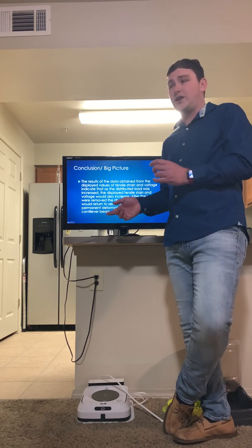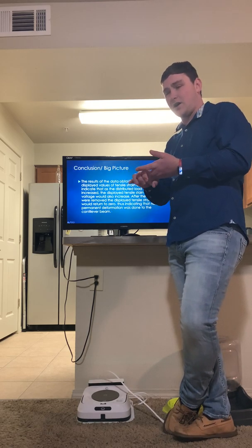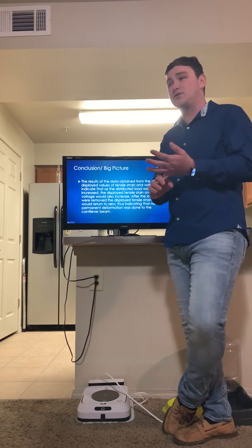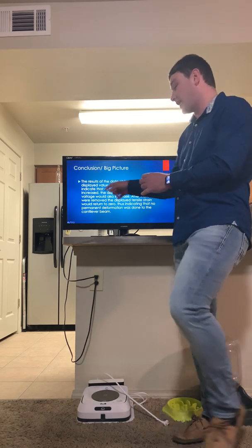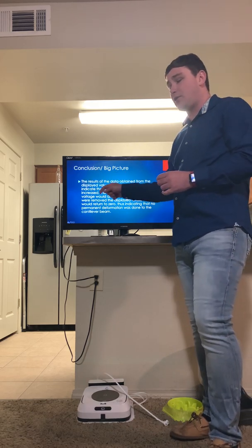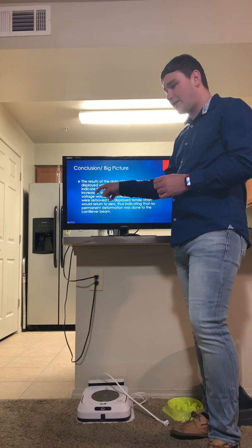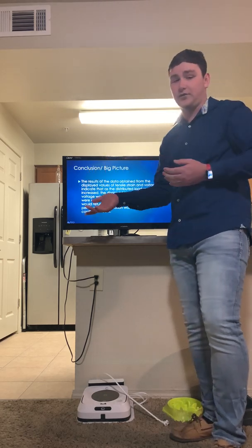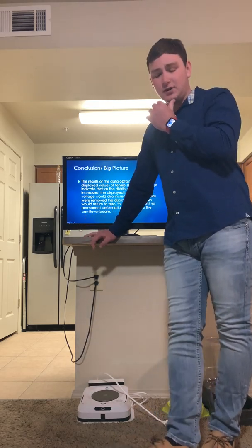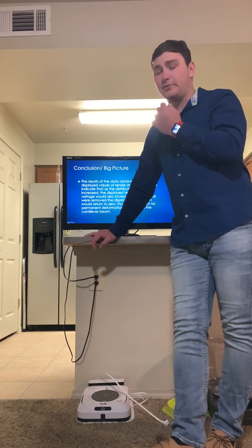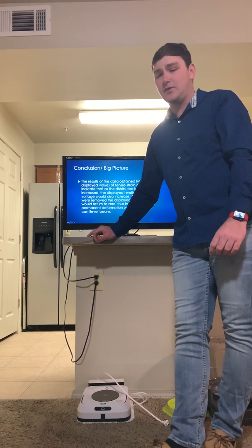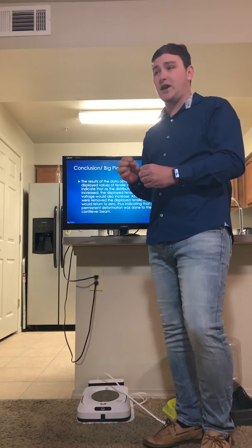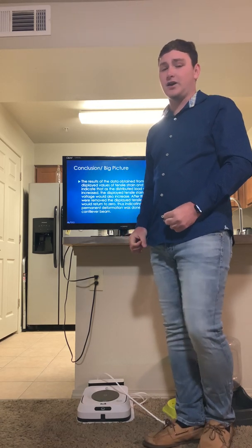So a few things I wanted to point out. A couple places the error in this experiment came from. The error came from not having the calipers, so we weren't able to get exact measurements along the cantilever beam to see exactly how far apart the weights were. And then also we weren't able to get a good starting and ending point because we didn't have the calipers. If we had the calipers, there would have been a much lower percentage of error than 45%. Also there was human error of adding the weights and making sure they're exactly in the same spot each time, at exactly the same distance. But calipers would have helped a lot.